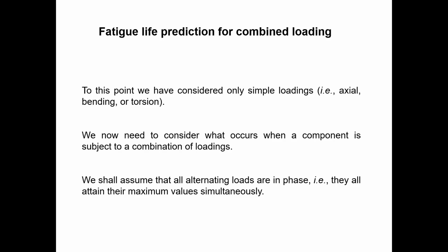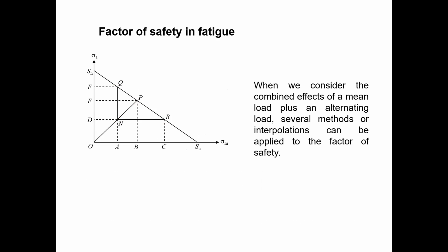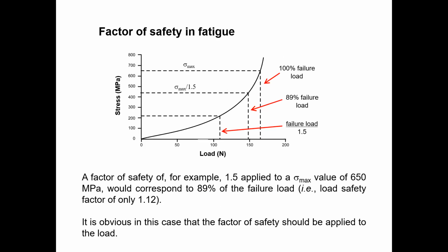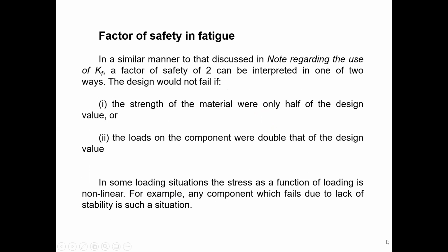There is another assumption. So many assumptions are there. In here, if you are going to apply the stress to find out the factor of safety, that particular loading condition should be linear with the stress. So it should be linear. The function of loading and stress should be linear. But if it is non-linear, you can't use stress. You need to use load value instead of the stress. So normally if you use stress, you will assume it is linear. So you need to mention it.